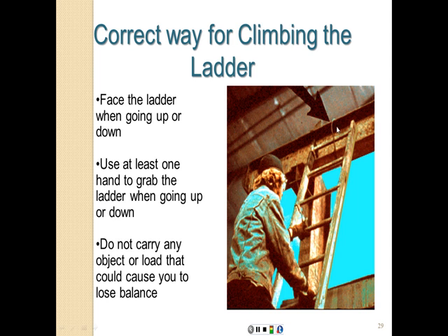And as you can see here, that does not seem like a landing surface, that's why we do not have the 3-foot extension, and we have it tied off properly here, and he seems to be maintaining the 3-point contact with the ladder. The slope seems to be okay as well, the 4:1 that we talked about.